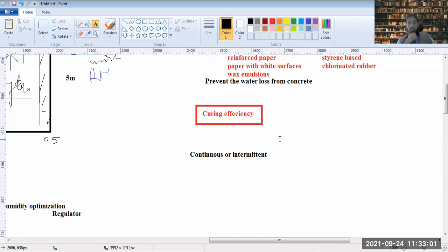You need to have concreting with an optimum amount of strength that you need to develop. So even in intermittent curing, you could achieve extra 70% of the strength that you want to achieve. But in continuous curing, you could achieve even 120% of the strength of the initial strength that it has. So continuous curing would always be good in all weathers, in all climates, but it is not possible at site in large structures to cure it completely at all times. And it also involves costs.